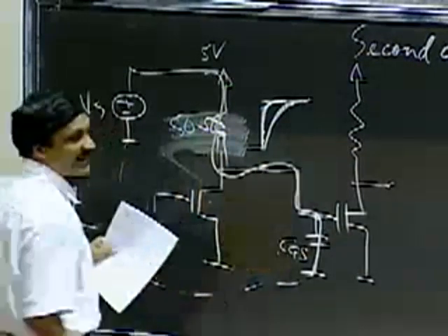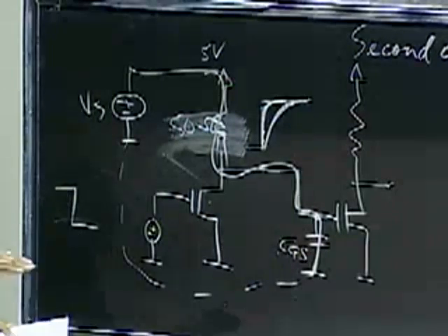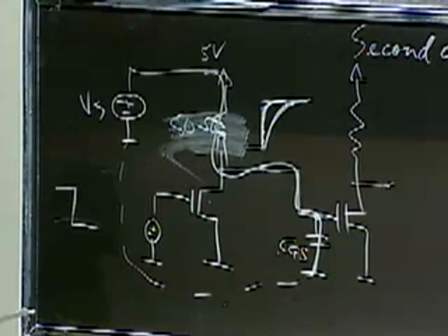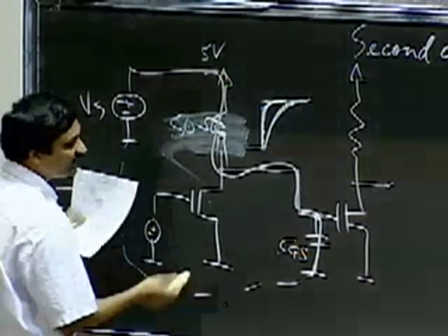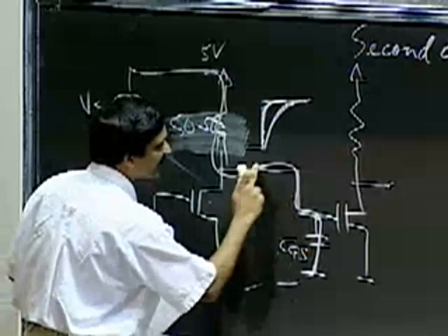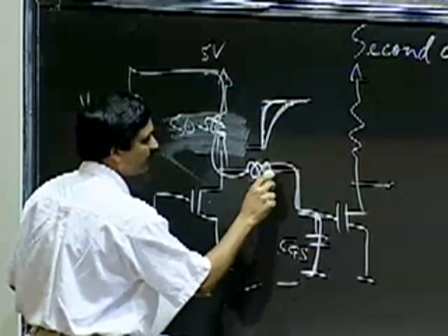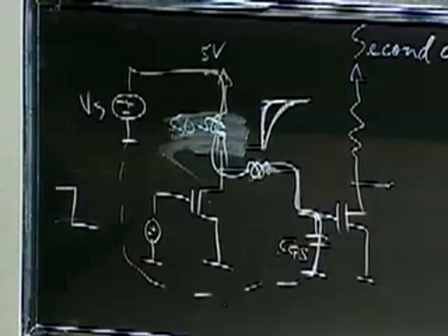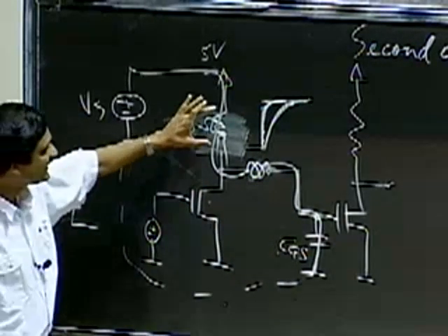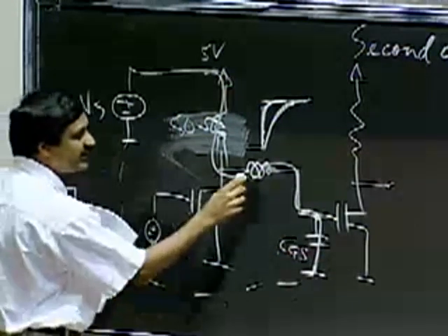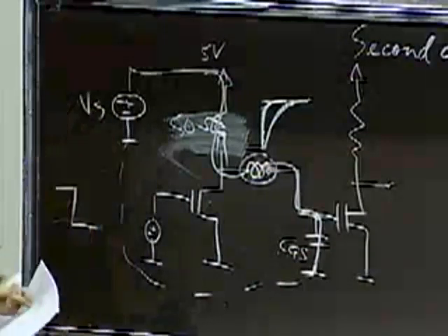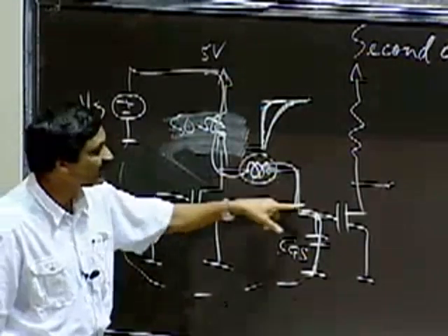And in fact, any current flowing through a wire above a ground plane, for that matter, can be characterized by an inductance. Okay, so I can model that by sticking a little inductor here. So my real circuit is not exactly a resistor and a capacitor, but my real circuit is an inductor as well that comes into play because of this wire.